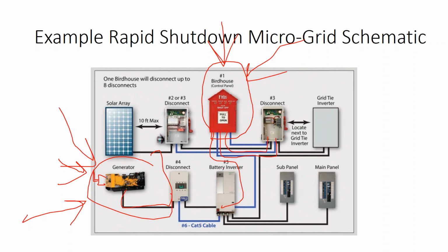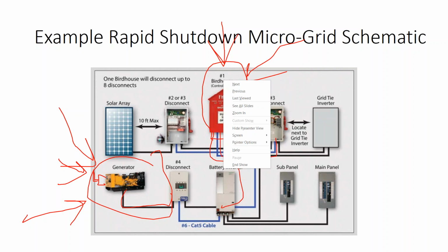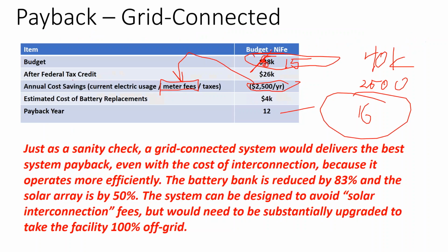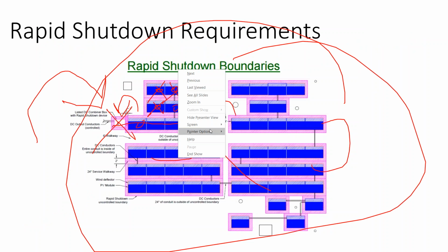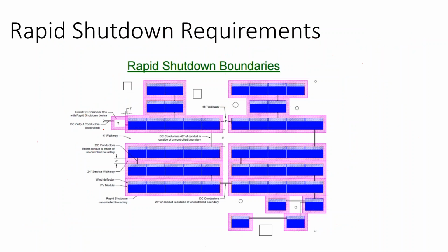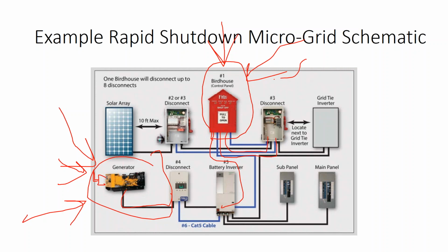So anyway, another thing to think about on this slide is, just like with these rapid shutdown combiner boxes, the way these rapid shutdown combiner boxes work up on the rooftop is that this is a DC system, and so you have a positive side and you have a negative side. There's no neutral involved. Well, on these rapid shutdown combiner systems, you'll still run a neutral wire up to the rapid shutdown box that's just used as a relay to enable the rapid shutdown functionality. Now you might have some disconnect switches that have additional intelligence built into them.